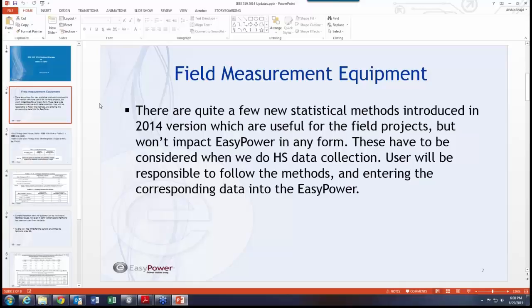You have to be able to explain why you chose the test data versus the data sheet from a manufacturer. And the calculations and all those things are rather more complex, let's say, versus load flow calculation. So that again brings us back to the point that it's not just EasyPower. You have to have good knowledge, and then you have to put EasyPower in use for you to produce good results. Otherwise, if you just make assumptions, if you just click a button and run EasyPower, it's not going to help a whole lot.